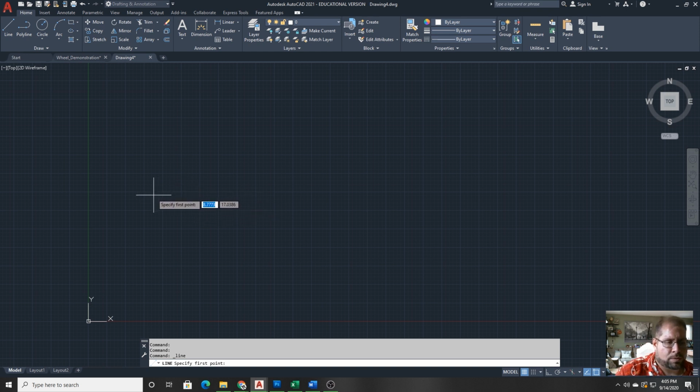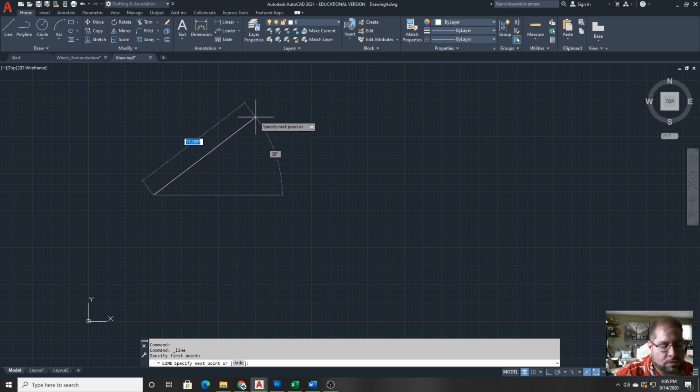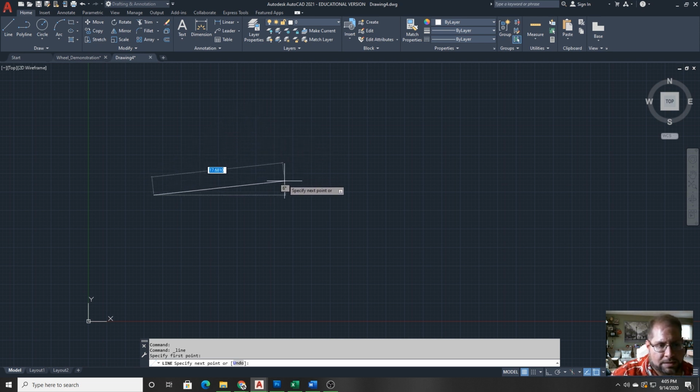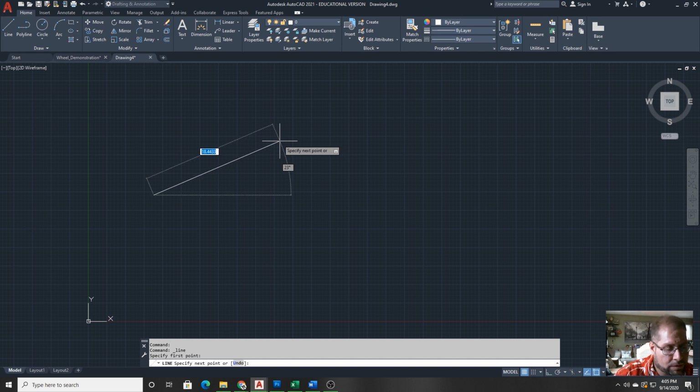After I click a first point, you can see on the screen through what's known as dynamic input a lot of data, such as the angle at which the line is being drawn, as well as the distance or the length of the line. Now, since we're using the pointing device again, or the mouse, it's not always easy just to get what you want, which is why it's going out to 4 decimal places with the length.